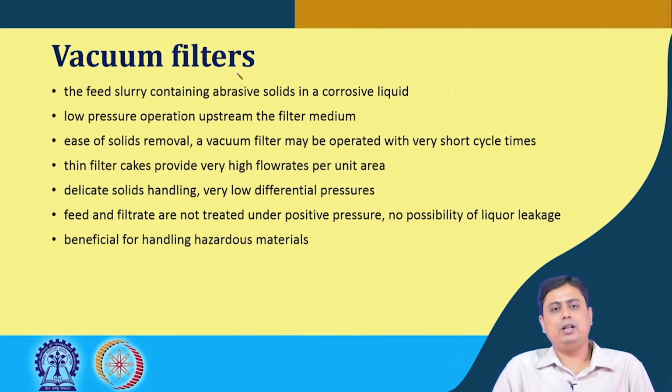It is also beneficial for delicate solids handling, because you can operate at a very low differential pressure, and since the feed and filtrates are not treated under positive pressure, there is no possibility of liquor leakage in the system, which is beneficial for handling hazardous materials as well.